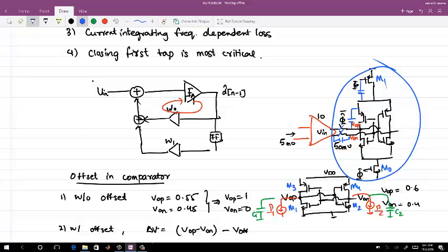Now, if this was happening directly at the V summing node, then the V summing node voltage will fluctuate, or the output will fluctuate because of this kickback. So a preamplifier is actually separating your V-summing node from the kickback. And you see the V-summing node also has all the other taps connected there, so the influence there is more. It can cause more, let's say you change the voltage and then you inject a current, and then it takes a while to settle because the V-summing node has a larger time constant.